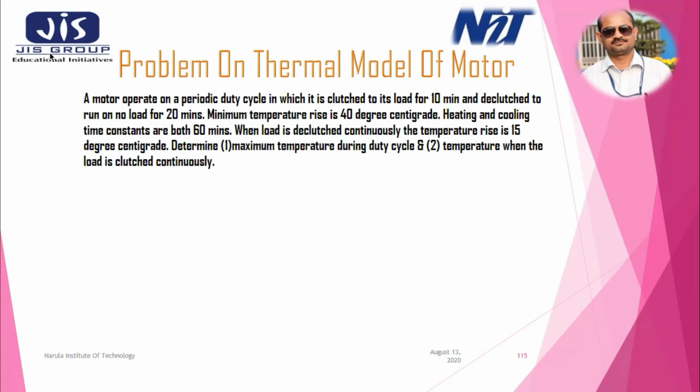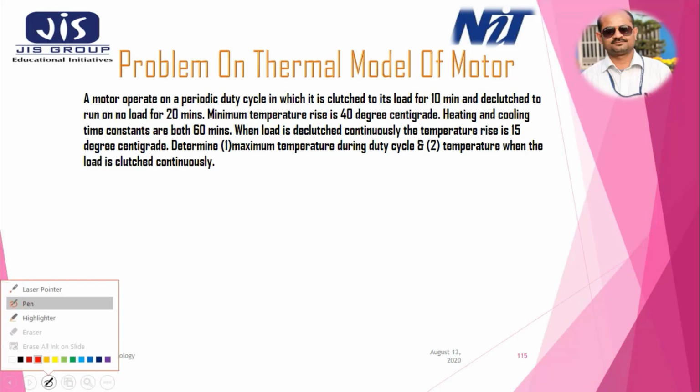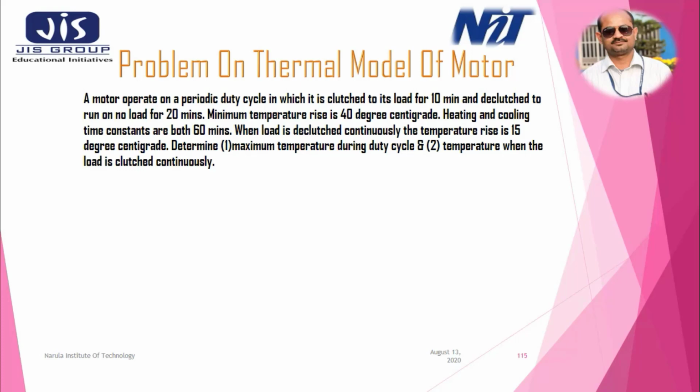Now what we know, my equation is theta equals theta ss into 1 minus e to the power minus t by tau plus theta 1 e to the power minus t by tau.